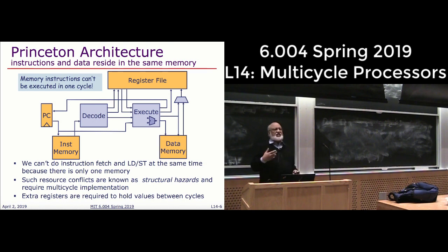Now, whenever you see this kind of a situation, that conceptually these things could happen, but they cannot happen concurrently because of lack of resources, because we happen to put them in the same memory. Such condition is known as structural hazard, right? You have created a hazard just because you don't have enough resources.